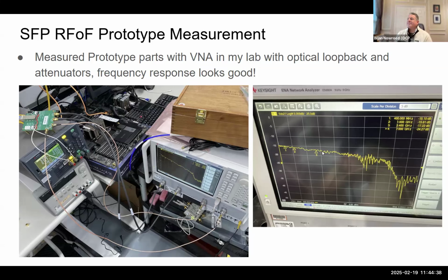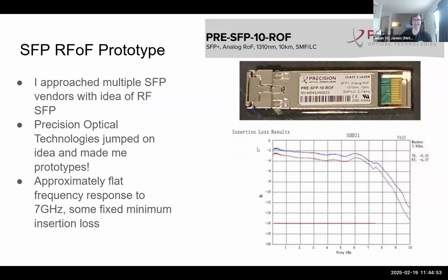So obviously the frequency response is probably not ideal, but up to about 2.4 gigahertz, this marker is pretty flat and has pretty low insertion loss. Again, this says 15, but I did other measurements that were more similar to this datasheet number. I didn't take the full S-parameter set, but at least the insertion loss was pretty straightforward. If that was your question. Yeah, that was my question.